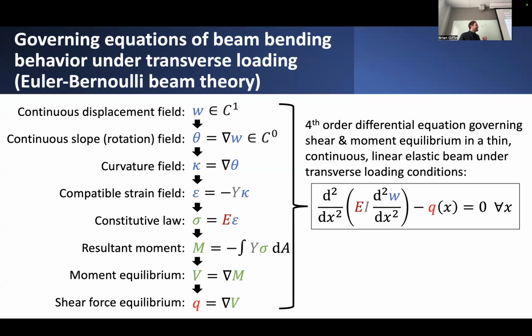And we can solve this fourth order differential equation to figure out what that transverse deflection field is, given whatever applied loads we might have put onto this beam, that possibly varying distributed load Q, and then we have some other things like the second moment of area I showing up here also, as well as the material property, the Young's modulus E.